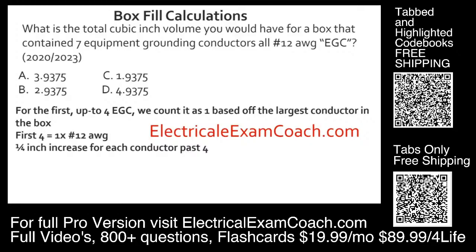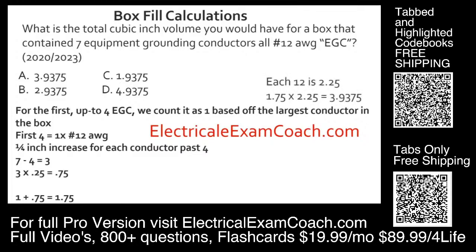Sounds complicated. We're going to break it down very simply. We have 7 total, and we're going to minus 4 because those first 4 we counted as 1. So we have 3 left over, and we're going to multiply those 3 by a 1/4, and that gives us 0.75. So we have a total of 1.75 conductors based off whatever the largest conductor is in the box. In this case, there's only number 12s. So we take that 1.75, multiply it by the cubic inch volume for a number 12 conductor, and we end up with 3.9375 cubic inches for our equipment grounds.